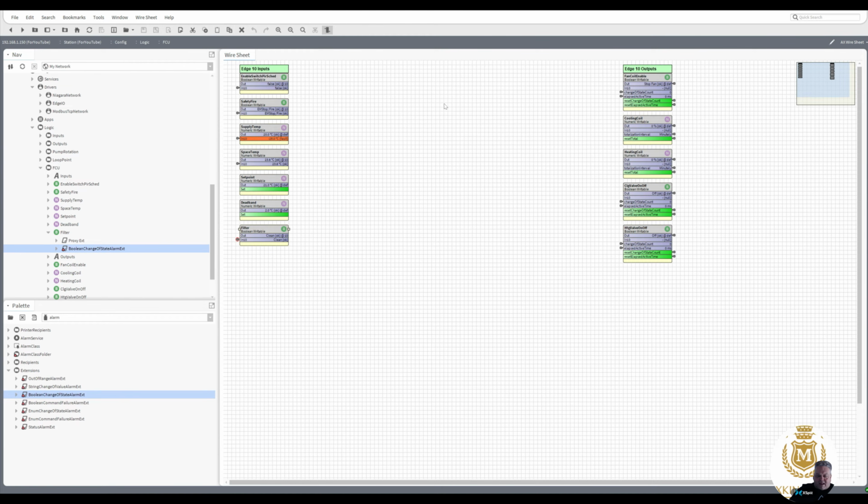So you can have them with one coil, you can have them with two. So you've got a fan, you've got your cooling coils, you've got a filter media, and they normally get changed depending how often the fan coil is used, but quarterly you would look at them, maybe half yearly. Depends what your maintenance regime is for your fan coils. But naturally you have lots of fan coils on the floor, so you could have 50, 60, 70 fan coils on the floor, and then you have an air handling unit feeding the fan coils.